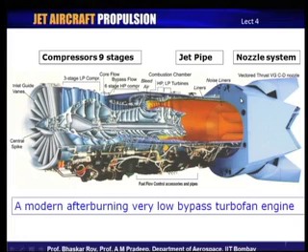And then you have a very complicated CD nozzle. This particular engine has what is known as vectored thrust, variable geometry CD nozzle. We will be talking about some of these issues later on in much greater detail, and these are the modern versions of the deployment of CD nozzle, in which you not only get a high velocity supersonic jet, but you have control over the direction in which the supersonic jet is released, so that the thrust generation can be controlled both in magnitude as well as in direction.